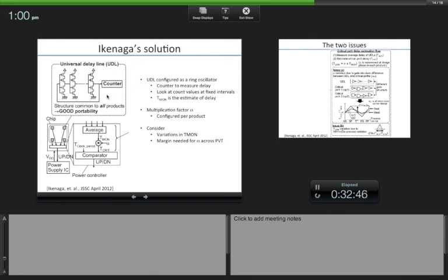When you do the measurement in this approach, you say, look, I'm going to count over a period of 1,000 cycles. Just like what we saw previously, where a timer gives you a certain time window in which to make a measurement, similarly there will be a timer which says, okay, start the counter, and let me see by the end of the timer how many counts have happened. That gives you an indication, and you know the time period because that is a fixed frequency clock. From that you can estimate the frequency here. So this is a digital approach, but you have to spend more time to make the frequency measurement.